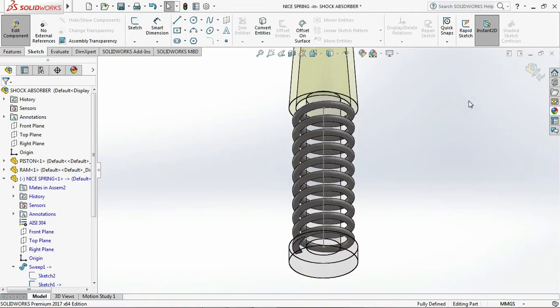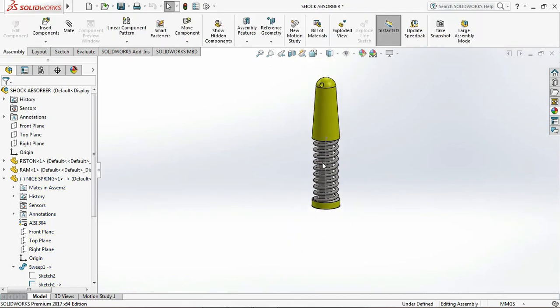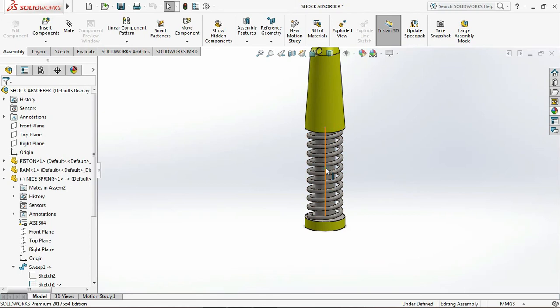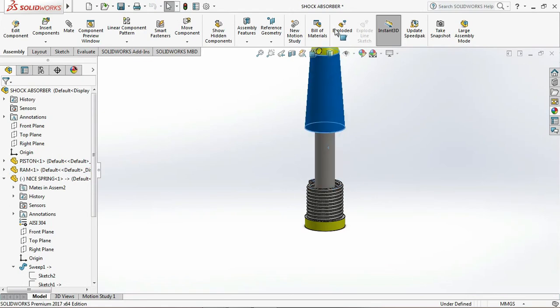Yeah, that's better. And exit out the sketch again, and you can even hide that one. And now, because that spring is fully defined to be coincident on the edge of this RAM, if you do like this and rebuild, the spring can respond positively. And when you do like that and rebuild there, the spring can go like that.